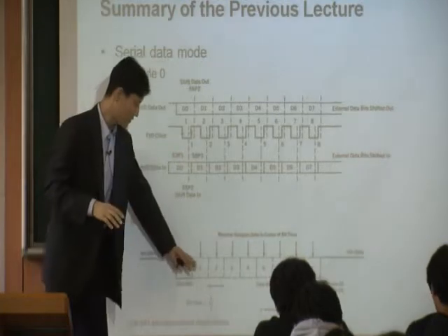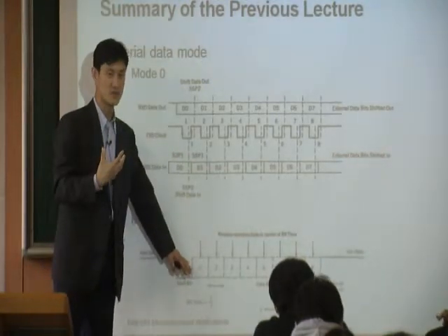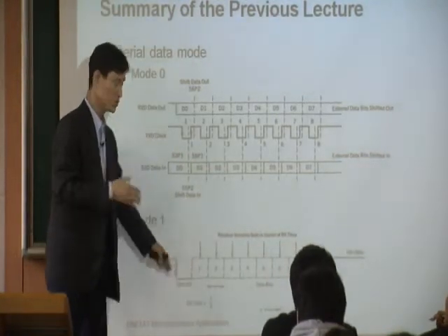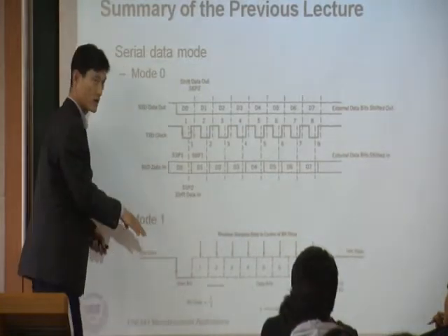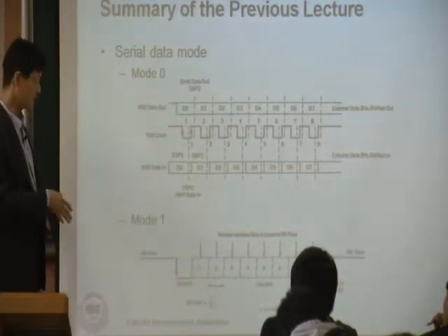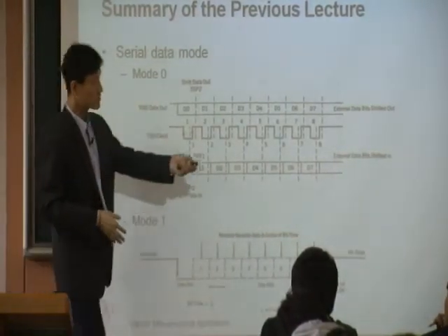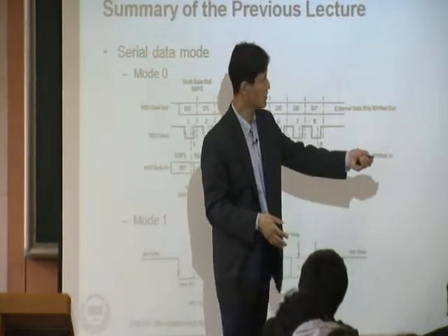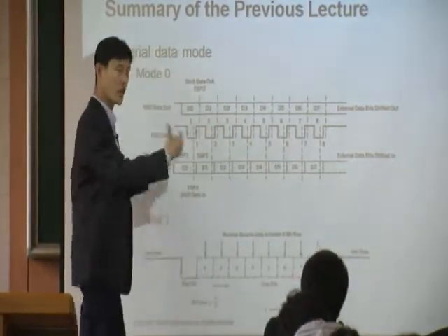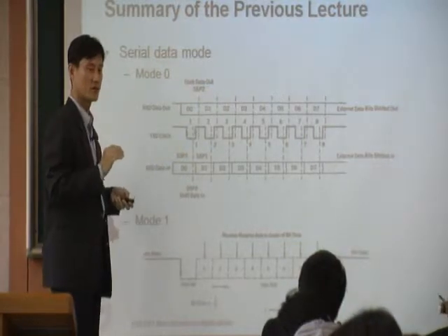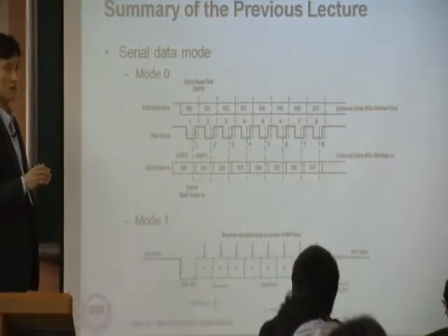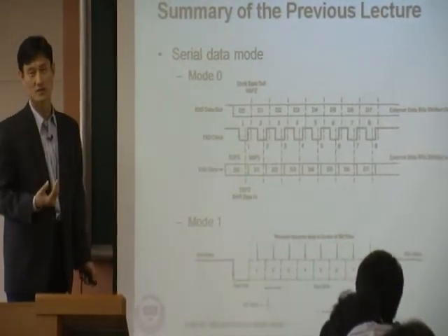Because without a start bit, again, the receiver can be confused. So you need to have an edge detection at the receive side. Therefore, we need a start bit. And because of this possible confusion, we need to have agreement on the baud rate. That's what you need in here. That's how we do communication.